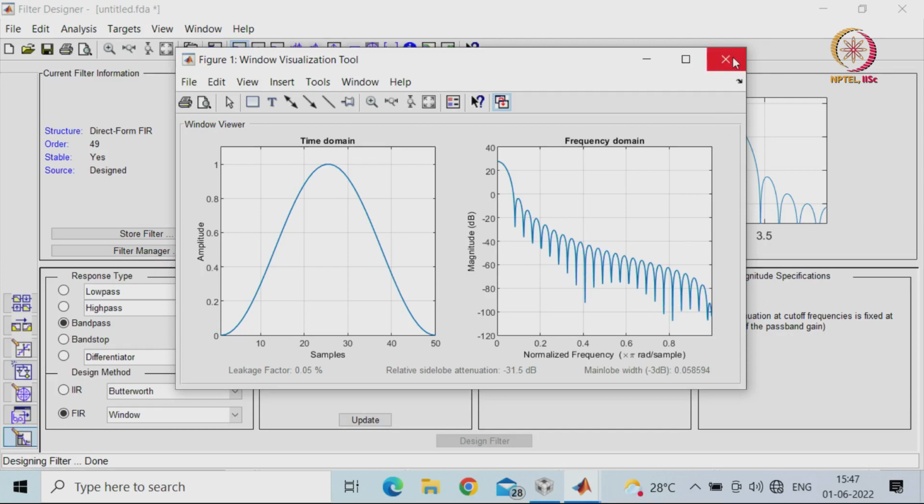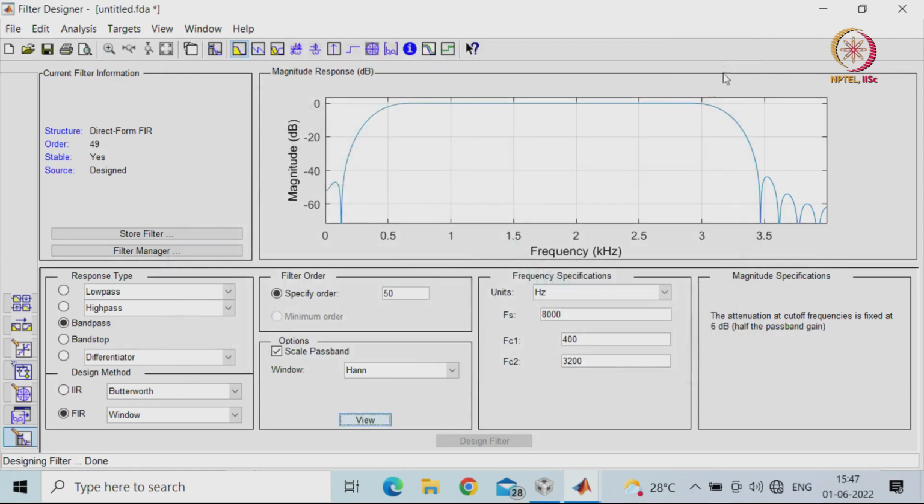So, this is how you can play with your design, and then you can use it in your filter design. You can use FIR 1 or FIR 2 to do the design, or these are the coefficients. One of the things you have to do, if you are using Code Composer Studio, is you will be seeing there is an IDE generation of coefficients.